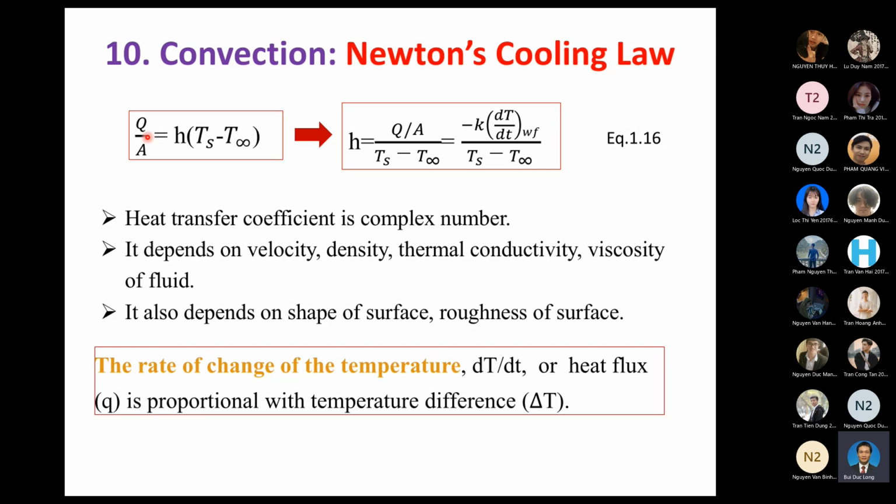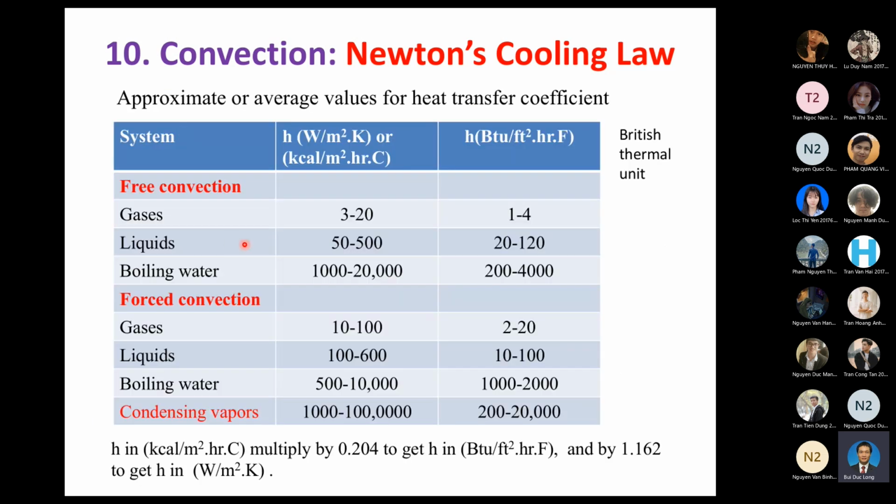If you use a fan, the H here can be bigger, for example hundreds, for forced convection. So the heat from the body will transfer to the surrounding environment very fast, so you feel cooler. That is the meaning of this heat transfer coefficient.